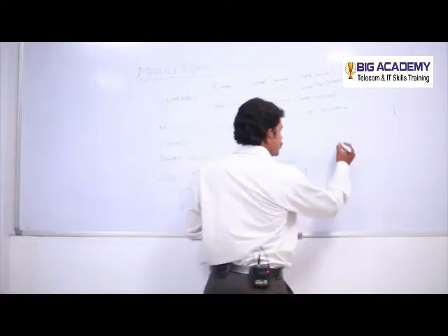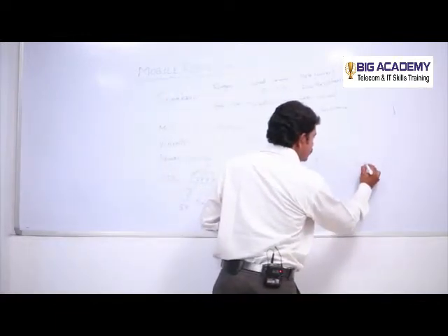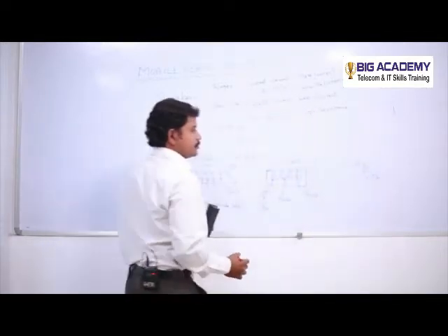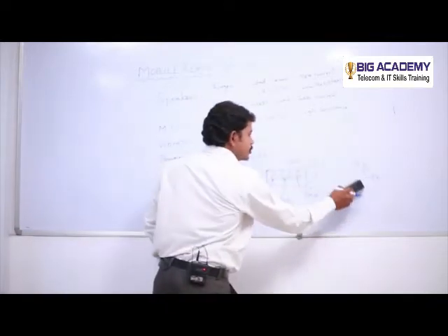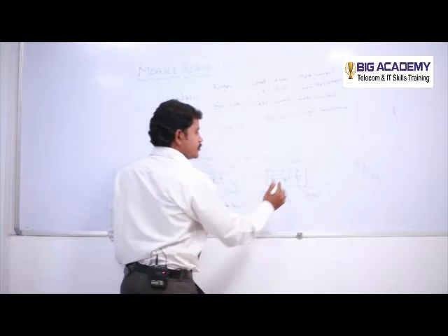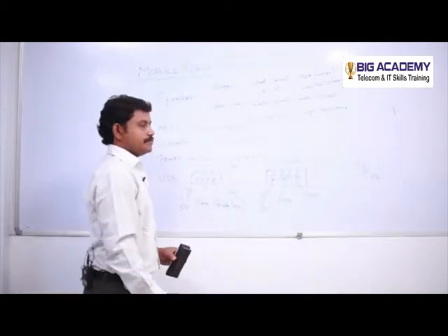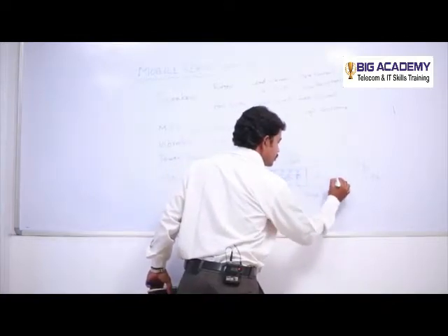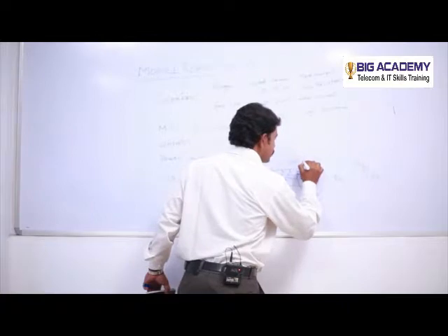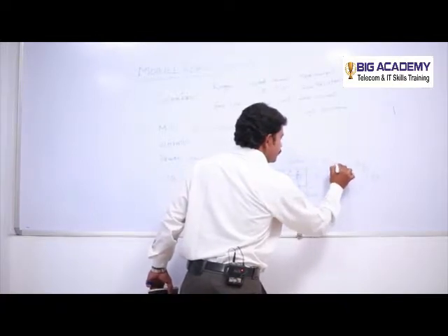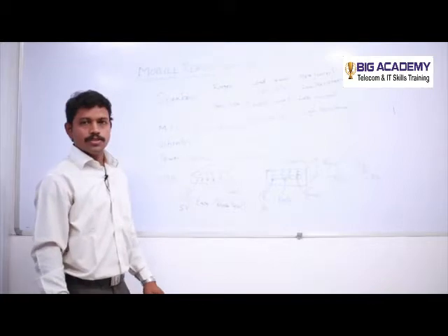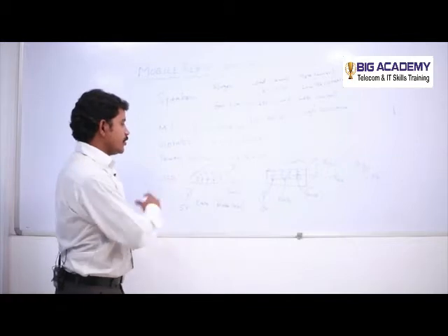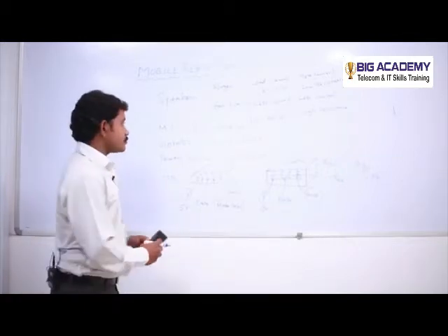The multimeter should be in this buzzer mode or in the diode mode, right? So in this position your multimeter should be placed, and for checking the ground connection you have to check this way. One red color probe should be placed here and the black color probe should be placed in the ground position or any metal surface, right? So in this way you can check the USB.